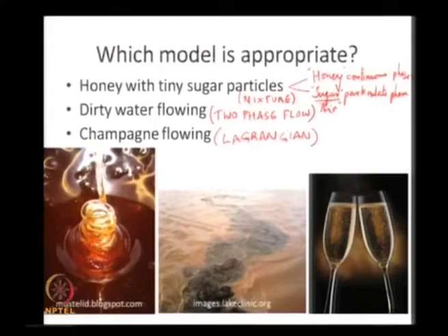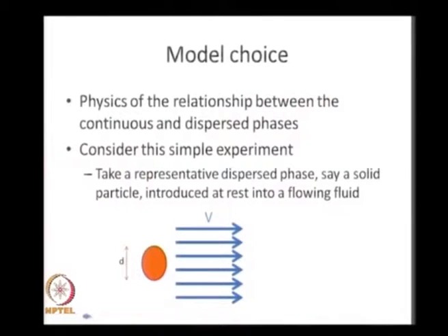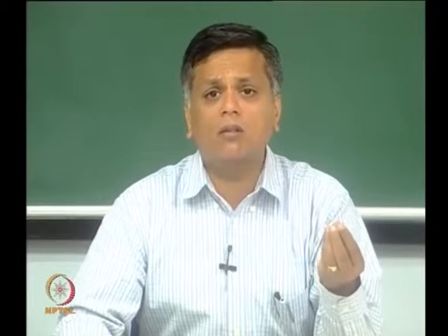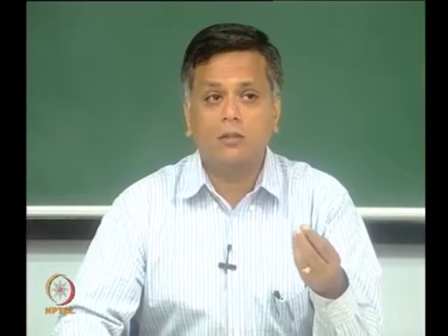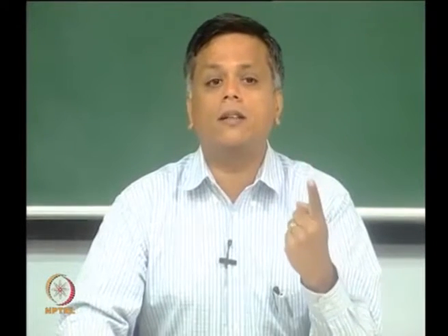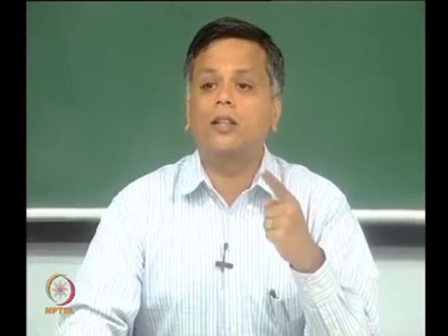Okay. All right. So, we will now move into a quantitative description of how to arrive at these modeling choices. We have the first model, which is the exact model that is valid in all two phase flow situations, except it is computationally intensive. We have the second model, which is the mixture model, which is valid in situations where firstly I can postulate a continuum for the dispersed phase,